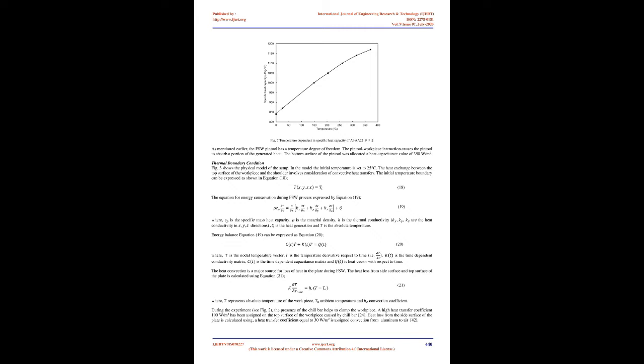The width of the workpiece in the developed model was decreased by trimming 112 mm from the plate's boundaries, which is at a distance from the weld line. The eliminated parts of the plate have hardly any boundary effect on the welding procedure. The dimension of the modeled plate is length 80 mm, width 40 mm and thickness 8.128 mm.